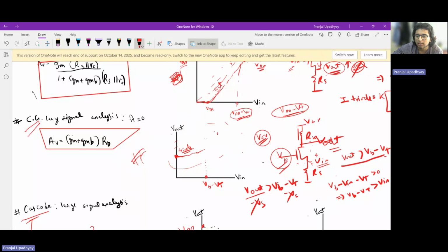That's why I'm saying again and again that you just have to check drain voltage with respect to the overdrive voltage, right? Overdrive voltage will basically be VGS minus VT, so I should better say VG minus VT. Saying it overdrive is not completely correct, but yeah. After this point, it transitions to saturation, and since I'm increasing my Vin, I'm still decreasing my current. My current again decreases sharply because the dependence on VGS is in the square form, and eventually my transistor becomes off.